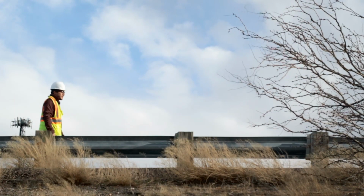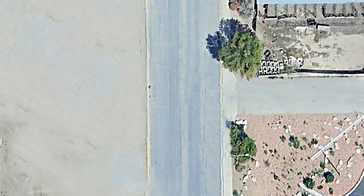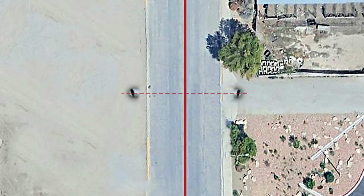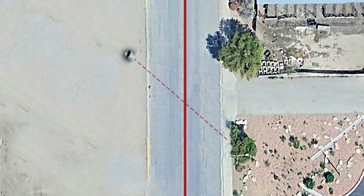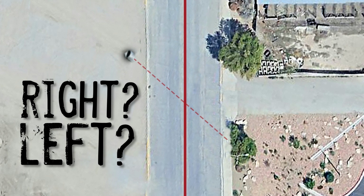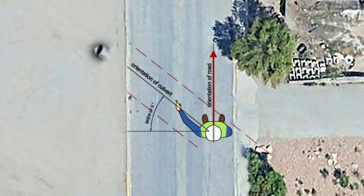Let's change the perspective. Another characteristic of culverts is the skew, that basically is the orientation of the culvert to the direction of the road. If the culvert is oriented perpendicular to the road, its skew is normal. But when the culvert is not perpendicular, we need to define if it's skewed right or left. To achieve that, let's position ourselves parallel to the road. By extending our arms, we can replicate the alignment of the culvert.